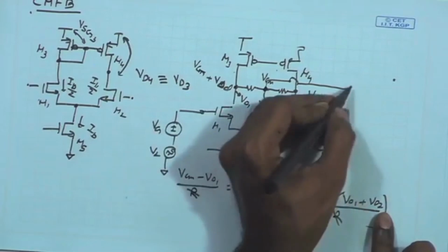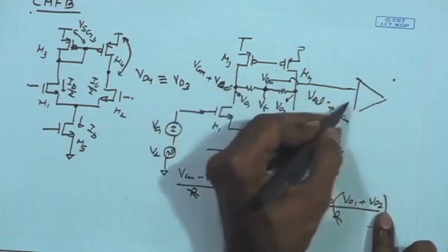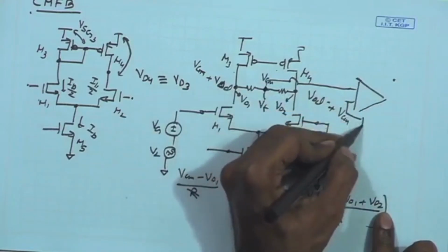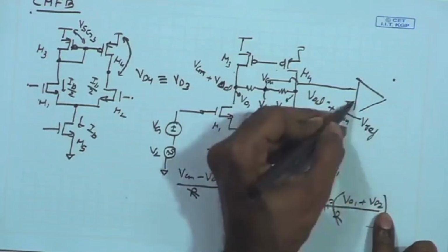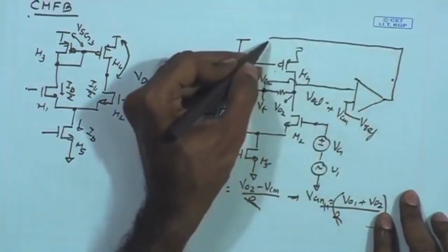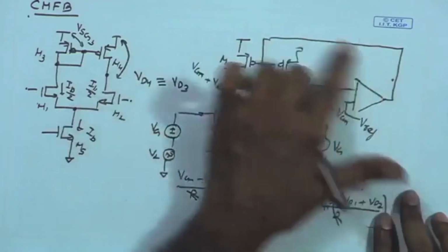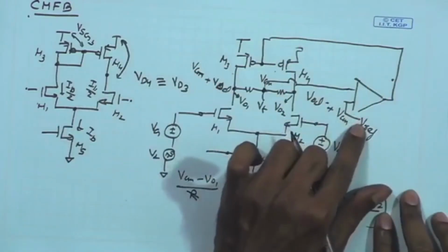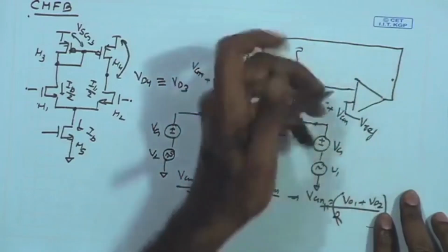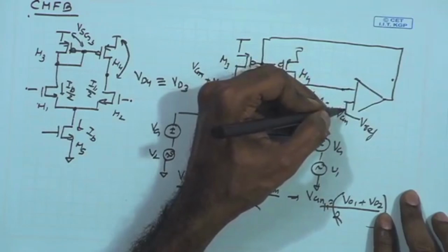Now, I can apply an error amplifier over here and try to put a reference voltage Vref at the terminal, and the output of this can be made to control the gate of the PMOS. And if I ensure negative feedback in this loop, the negative feedback stabilizes the input voltage at the positive terminal close to the negative terminal or vice versa.